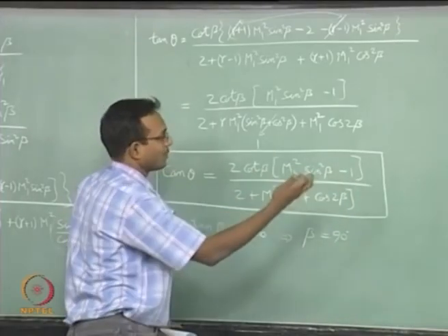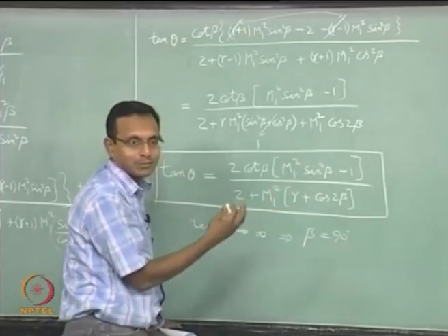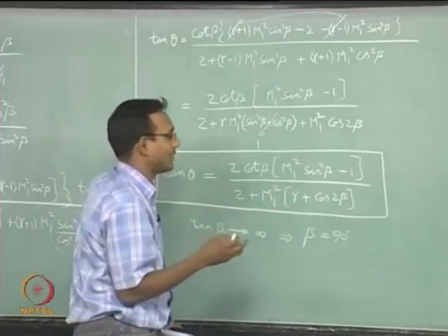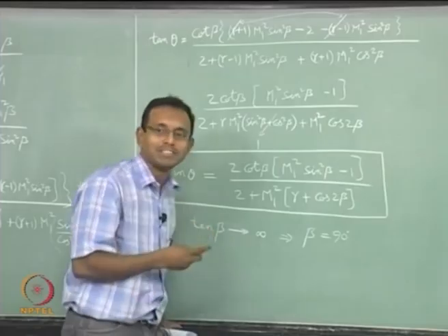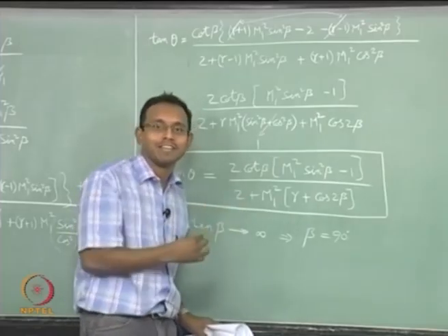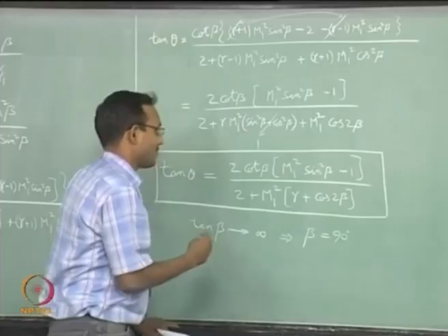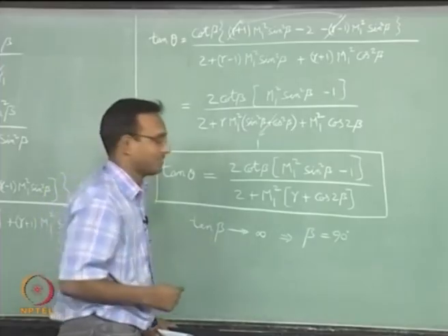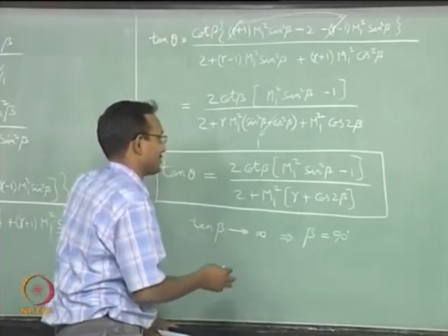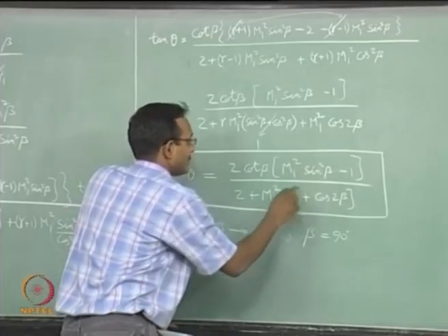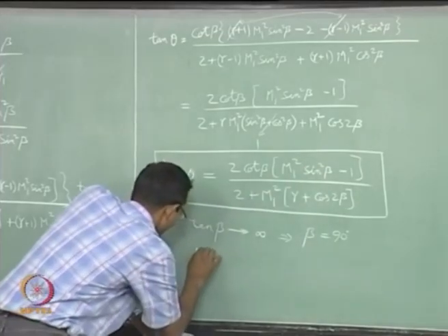So, I will take a square root of that, it will still be plus or minus 1, minus 1 is not possible. So, we will keep it as plus 1, minus 1 just simply means that the flow is from right to left instead of left to right. Mach number negative does not make sense for us, it is just absolute value of velocity for us. So, I will just have one solution for it,